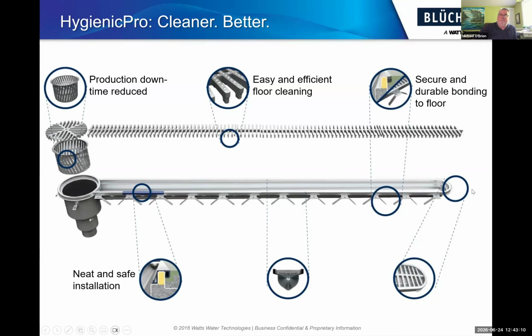There's plywood within the channel, again keeping it clean, so it saves the installer the time of going and buying boards to cover the drain. But this also creates, as you can see, once the concrete is poured to this level, it makes sure that the floor level is higher than the surface of the drain. Very important for getting water to go down it.